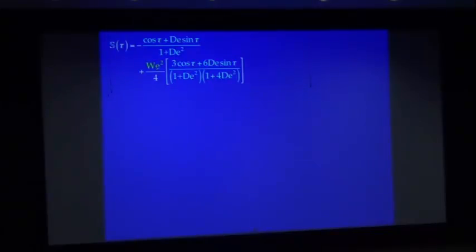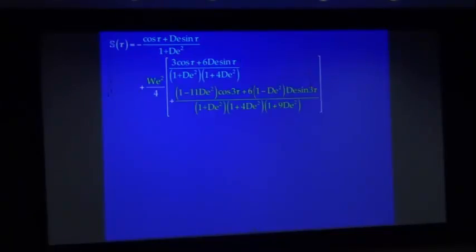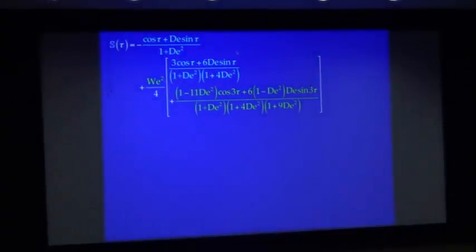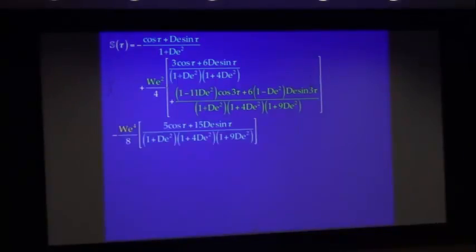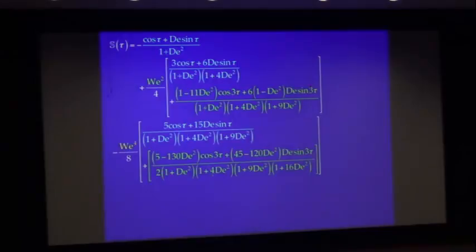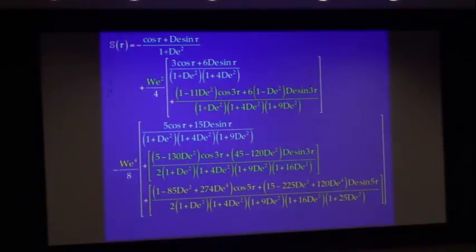But you see the blue part there? That's the nonlinear part of eta prime and eta double prime, but what comes along with it, sure enough, and that was a special day for me, the first time I had an equation for the third harmonic. The coefficient, you see out here, that's the amplitude. You see, that's the amplitude of the third harmonic, and it goes with the Weissenberg number squared. And now let's work out that third integral. You see, each time we get an improvement to the first harmonic, and then now an improvement to the previous new harmonic, and now an equation for the fifth harmonic.